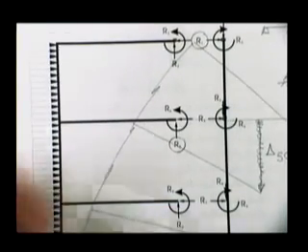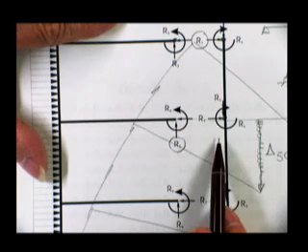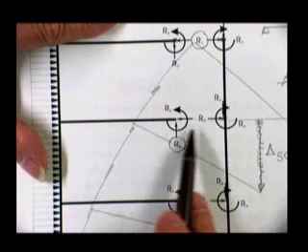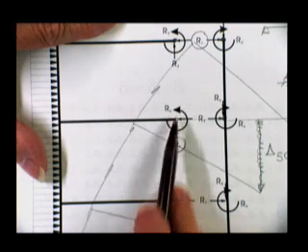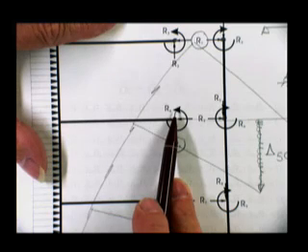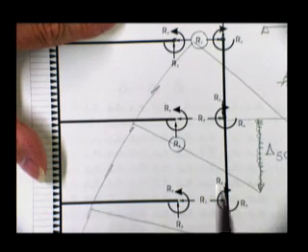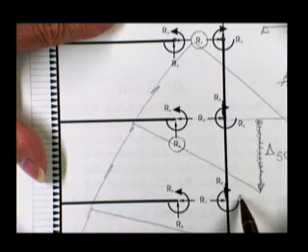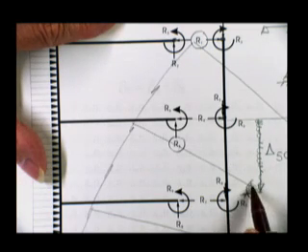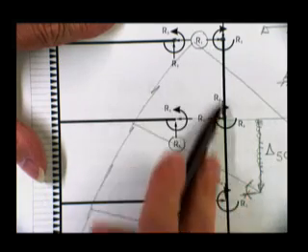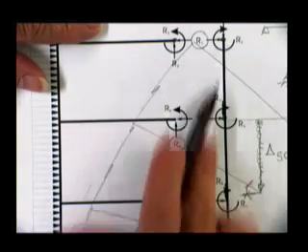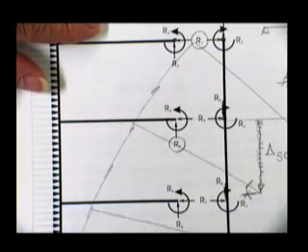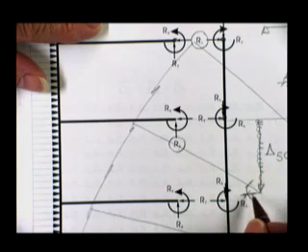All right. So when you're looking for delta 6, 0, here's your number 6 load, your number 6 position, your number 6 deflection. Delta 6, 0 would be this angle right here, added on to any angle that this guy causes due to the real load. Since the real loads didn't actually get over to this structure, he's just going to stay vertical. And therefore, this number right here will be delta 6, 0.